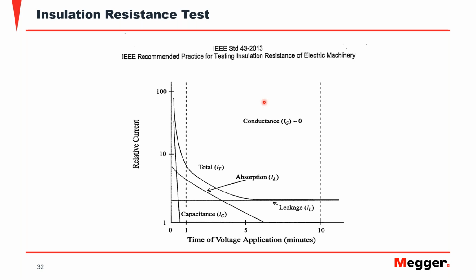So what I'm trying to say is that when you're doing insulation resistance tests, you have to give time for those processes to stabilize. You cannot wait forever. So you have to choose some time to perform that test, and since the results are going to depend on how long you wait, what you have to do is choose a standard time. We'll talk about this a little bit later, but keep that in mind.